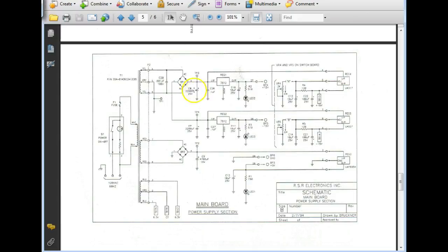Here's my input filter for the regulator. Here's my output filter for the regulator. Here's the little LED that comes on when you turn your trainer on, and this is the little terminal plug for plus 12 volts. Same thing down here. And notice the LEDs turn the other direction, right? Notice here we just blew up this capacitor right here, so this symbol's drawn wrong. Why is that? It's polarized, yeah.